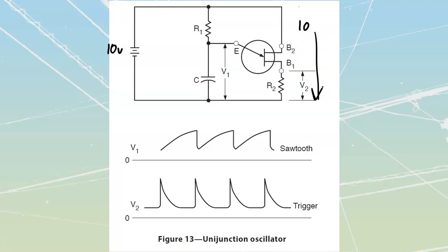We're going to have another resistor placed in line with this. And then we're going to have an RC timing circuit. Now you can place this down over here, or you can place this one up top over here. More commonly, you'll see it placed up top over there so that this B1 terminal is referenced to the same as this cap, because that cap is going to be your control device. It's just poorly drawn, but it's not critical inside of our circuit analysis, so we'll leave it there this time.